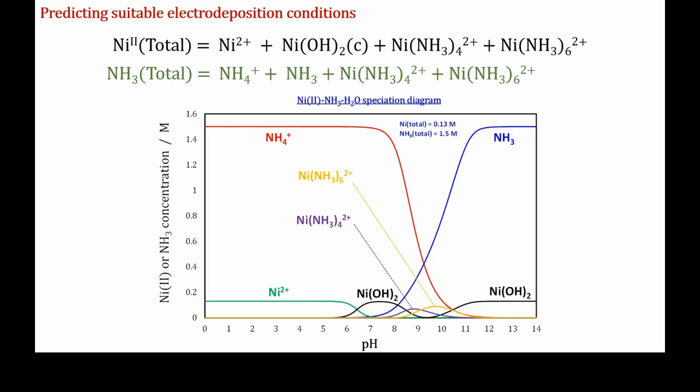And this includes anything that you will frequently come across in plating baths, like citric acid or citrate, and ammonia, right? And the idea is that they complex the metal to such an extent that it stops the hydroxide from forming. And you can have this wider range of plating bath conditions under which you can do electrodeposition or whatever.